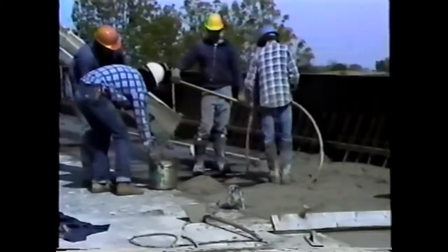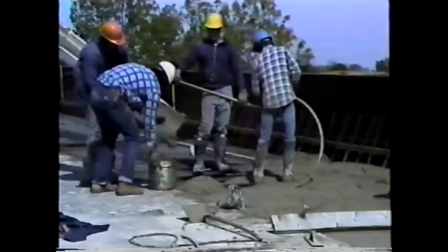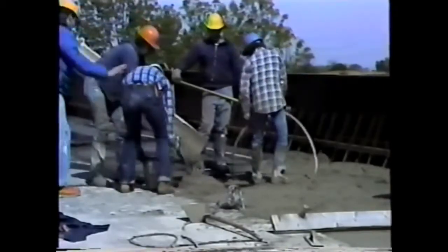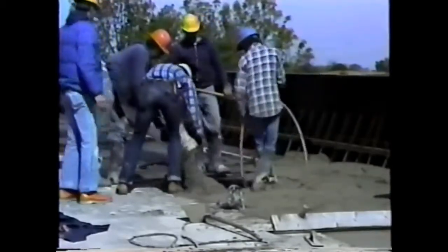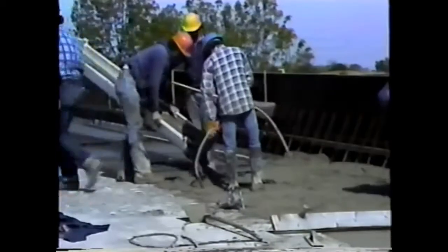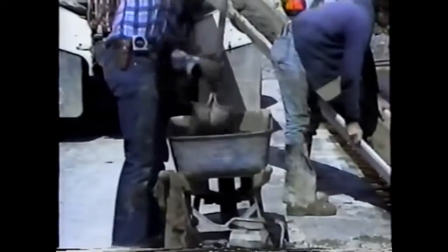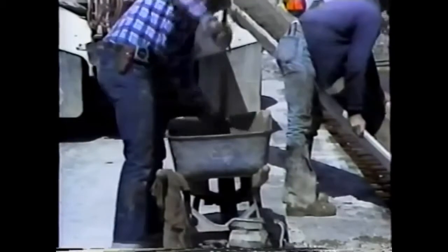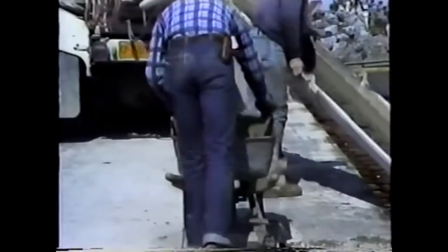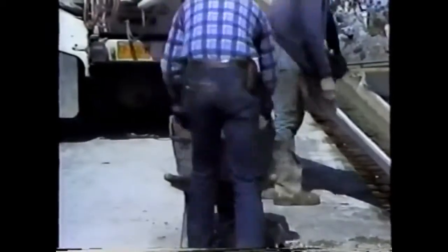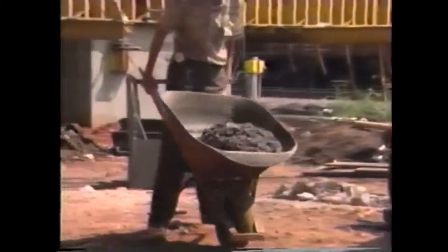Cutting the stream in half, like this, is unacceptable. The rim of the bucket will knock some of the large aggregate out of the sample. The sample should be mixed with a shovel just until it has a uniform appearance. Then it should be covered to protect it from the sun and the wind. Samples must not be allowed to dry out. One last point. Testing must be completed within 15 minutes after obtaining the sample.